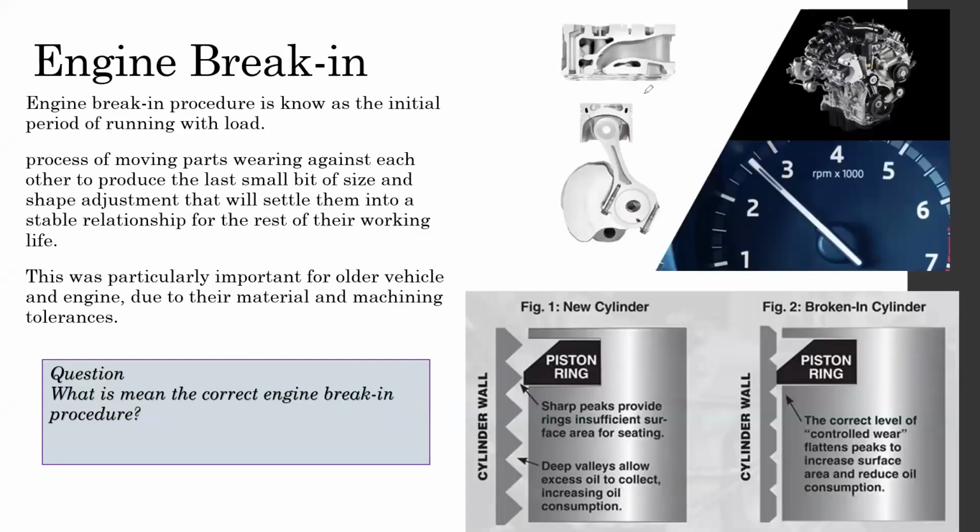Okay, so after starting for the first time, assume that we have completely done everything as we discussed earlier. Then what should we do? I think you might have heard this after a rebuild: the engine has to be broken in. We shouldn't run the engine hard. We have to run it very smoothly for a few thousand kilometers. There are sayings like that.